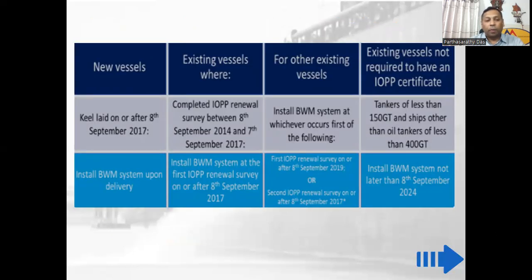Now, the ballast water management convention: how will it be implemented on ships? Here we can see the implementation criteria for new vessels, which are identified as those whose keel will be laid after 8 September 2017. They must install a ballast water management system upon delivery.